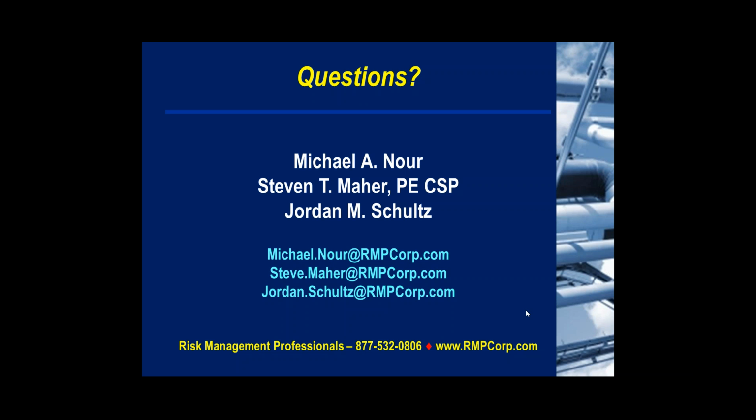So the point I'd like to make is that companies with a good MI program should already be tracking their failure data. If they have pinhole leaks, they should be tracking that information and identifying what the causes are. If you have all that data ahead of time in an organized fashion, ready to present to the PHA team, it would make the transition a lot more smooth.